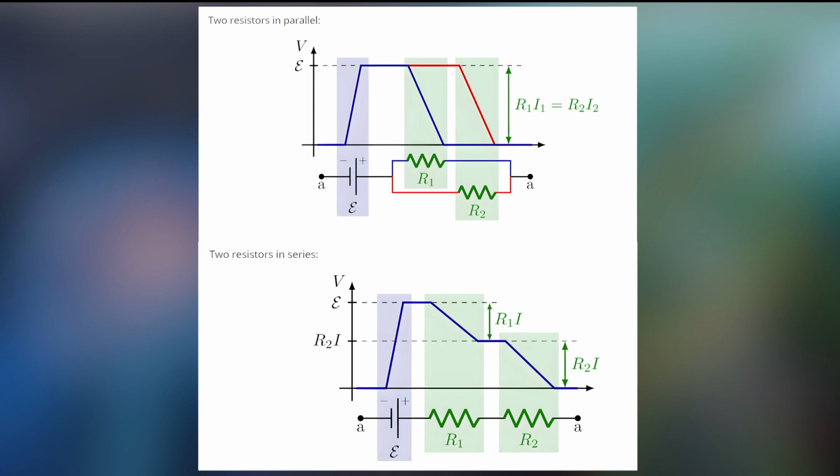So if you have a bunch of lights that are connected in series, and you find they're not working, it might mean that the whole thing is broken. It could just be a single bulb has gone, and therefore the whole circuit of lights no longer works. And so you have to go through the tedious process of looking at every light bulb and figuring out which one has blown. So generally, more expensive ones will probably be wired up in parallel, which is what we'll talk about next. So parallel circuits are different to series circuits.